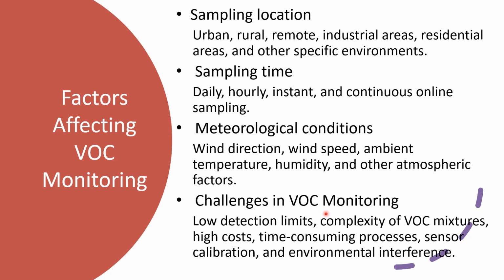There are challenges for VOC monitoring because the concentration is very changeable, lower or higher, and there are many kinds of VOC, so it is a very complex mixture. If we conduct VOC monitoring, it needs a little bit more cost, higher cost, and the measurement needs a lot of time and laboratory work. And also the calibration and other interference.